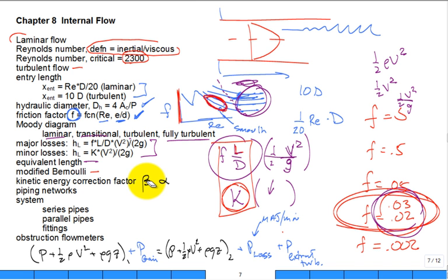Alpha. And that alpha goes right in this term right here, alpha. And right in that term right there. It was a little bit where you're using the average velocity, and you have a velocity profile, and each little chunk of fluid has its own kinetic energy. Luckily, what is alpha often equal to? Close enough to 1, a little over 1.